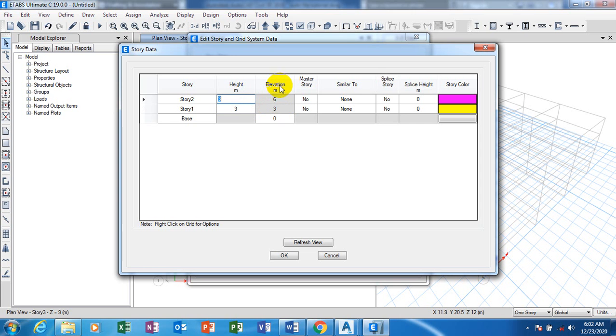So you can see the elevations here telling you that at the ground floor, from the DPC down to the headroom, you are having 3 meters. Now from that slab, top of the slab to your ceiling, you're having another 3 meters. So at that ceiling height at the first floor, it's actually 3 meters.